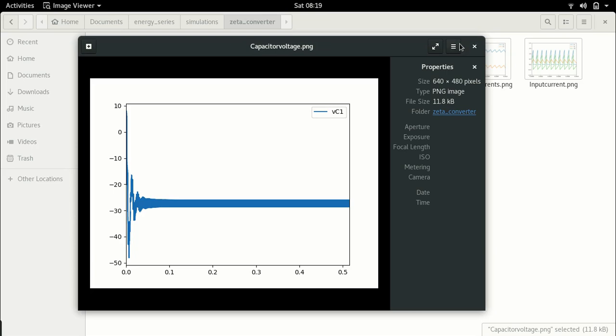This is just a kind of dry run if you want to insert a PI controller within this simulation to regulate the output, or rather regulate the duty ratio, right? Because the open loop control merely varies the duty ratio in some arbitrary manner, but in reality you would need a PI controller that measures the output voltage and regulates the duty ratio.